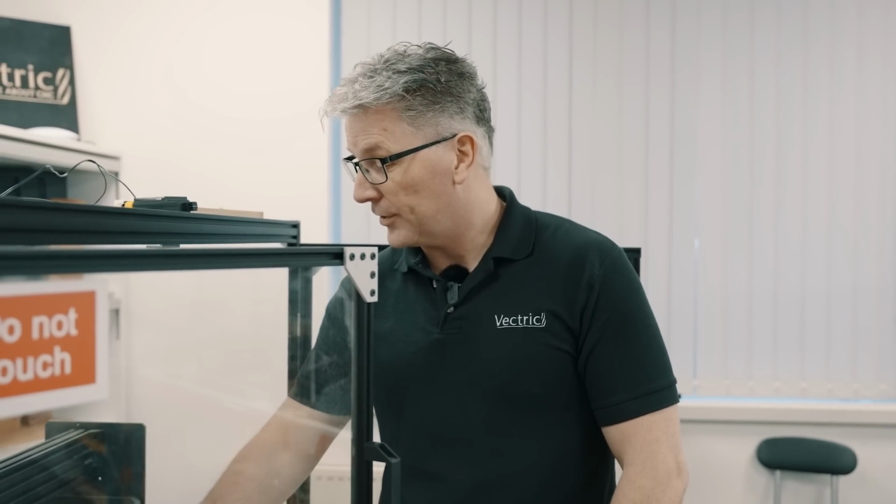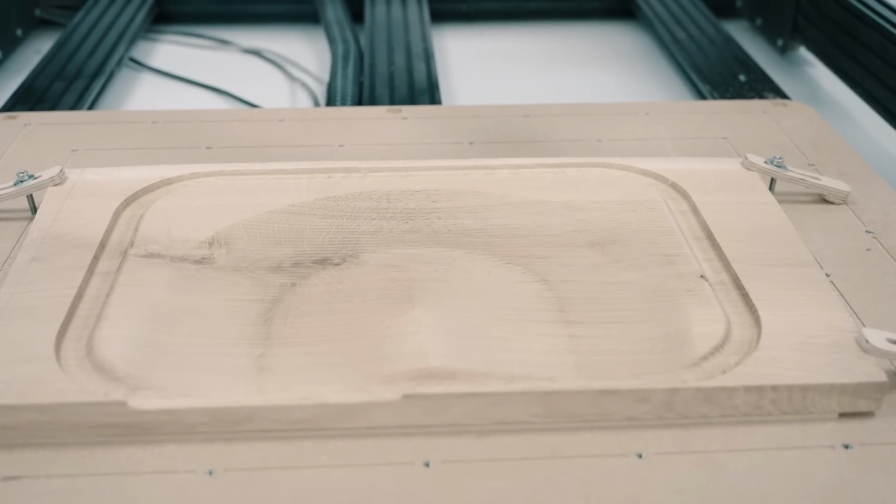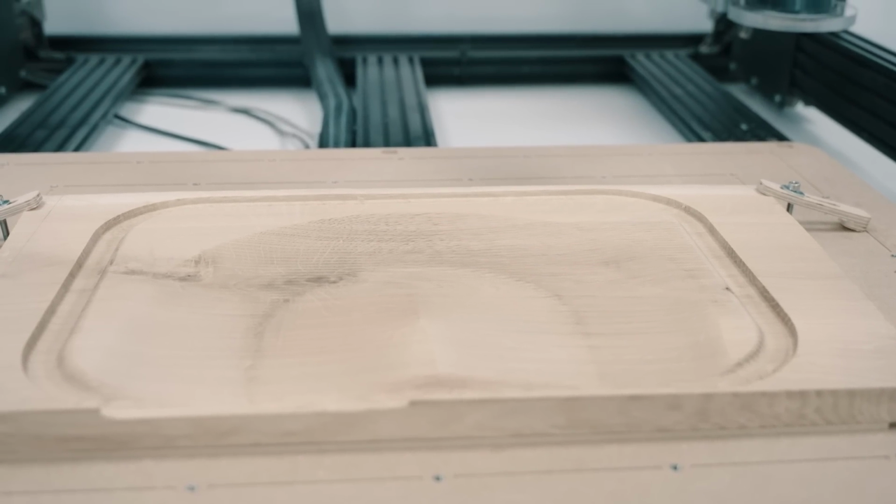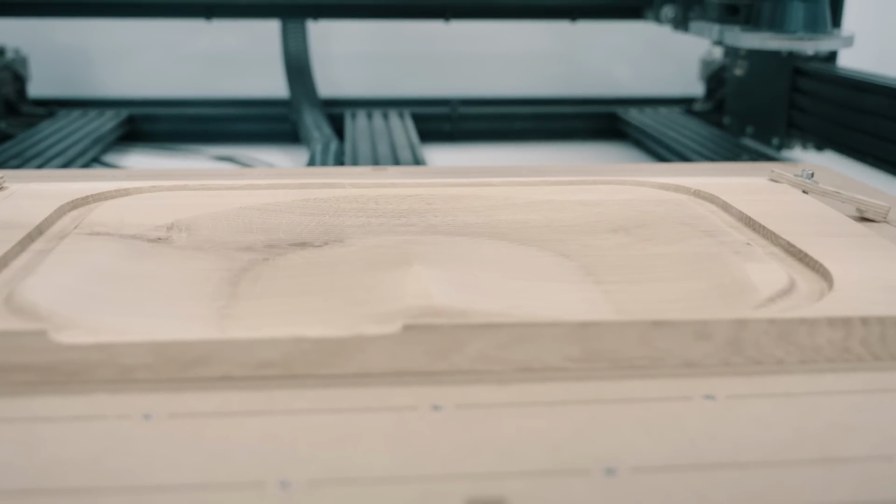That cut pretty good. The board wasn't entirely flat, so there are some flat spots on the top, but I don't think that's a bad thing. It's supposed to look a little rustic. If I was going to do it again, I might actually skim the top of the board first, but overall I'm pretty happy. So let's just change the bit and run the cutout pass.